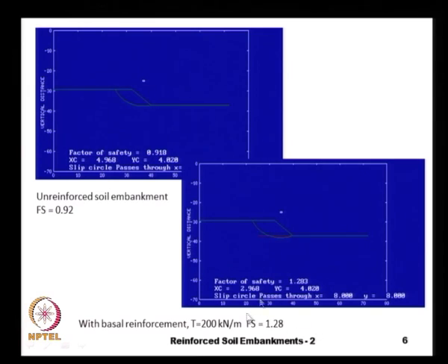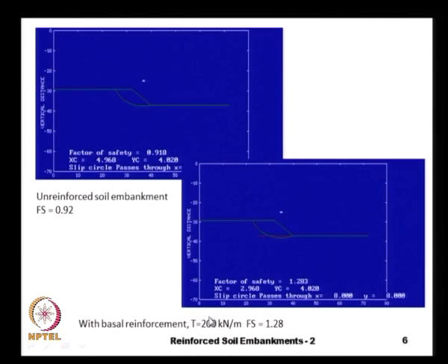As I mentioned earlier, if we are not happy with this factor of safety, we need to increase the tensile strength of the reinforcement, and typically we do not provide one single layer as illustrated here. We may provide 2 or 3 layers so that we can achieve our target factor of safety.